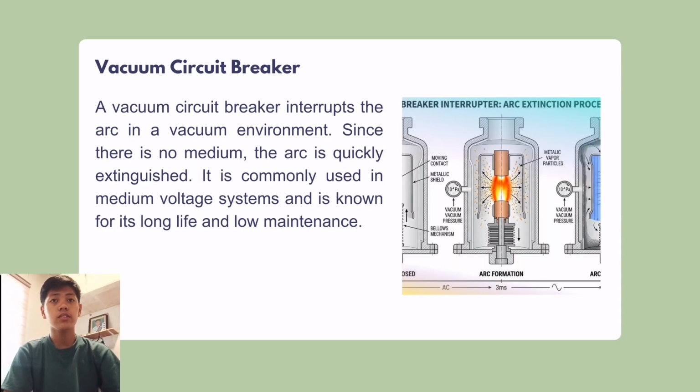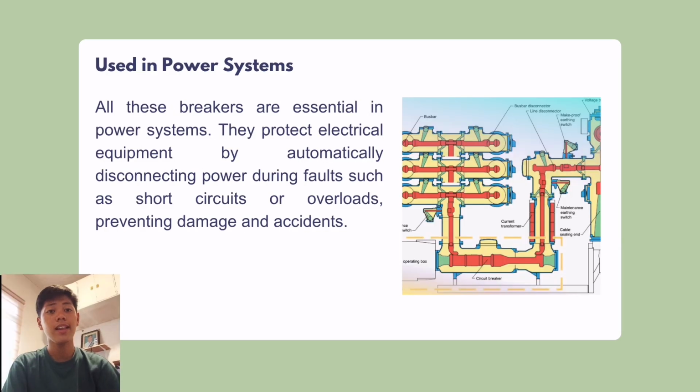The fourth picture is the vacuum circuit breaker. A vacuum circuit breaker interrupts current within a vacuum environment where the absence of gas prevents sustained arc formation. It is commonly used in medium voltage applications and is recognized for its high reliability, long service life, and minimal maintenance requirements.